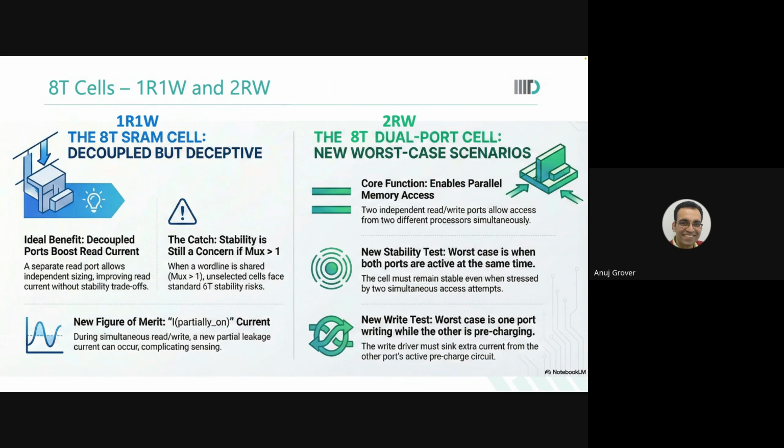Now look at what is happening. I have turned off pre-charge of everything. So over here, there is one stored. So this particular bit line will remain stable. This particular bit line, because I am reading this, will discharge. This particular bit line, one was stored, it wants to remain stable, but the adjacent bit line is discharging. Coupling between these two will result in this also discharging a little.